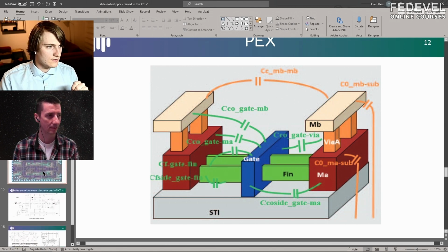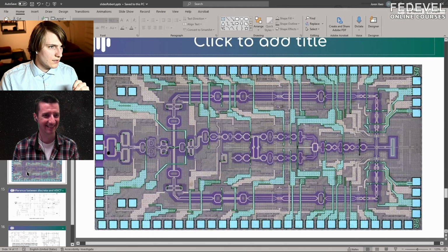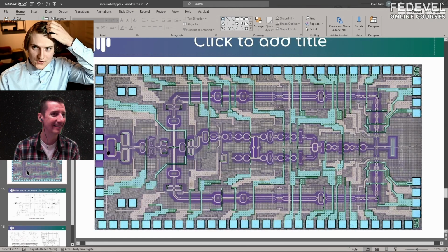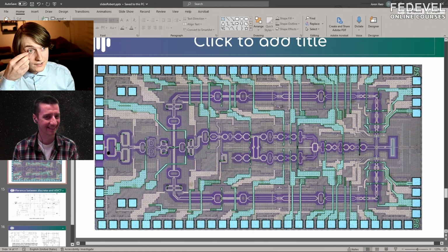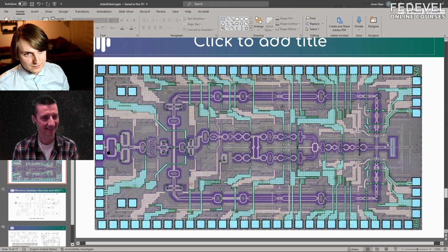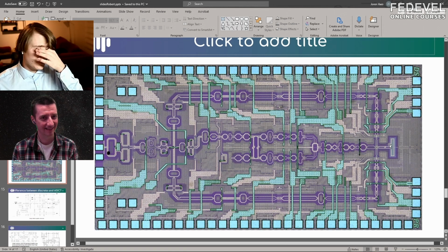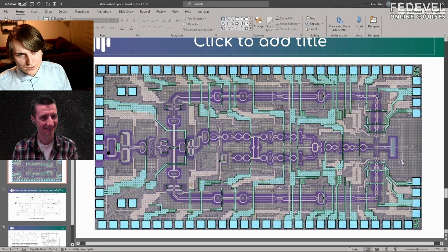What I then have is, this is a nice example. So this is what a terahertz chip looks like. This is made by a colleague of mine. And so on the right here, this is an antenna. I think this works, oh, he's going to be angry at me if I get this wrong, but I think it's 460 gigahertz. So this is your folded dipole on the right.